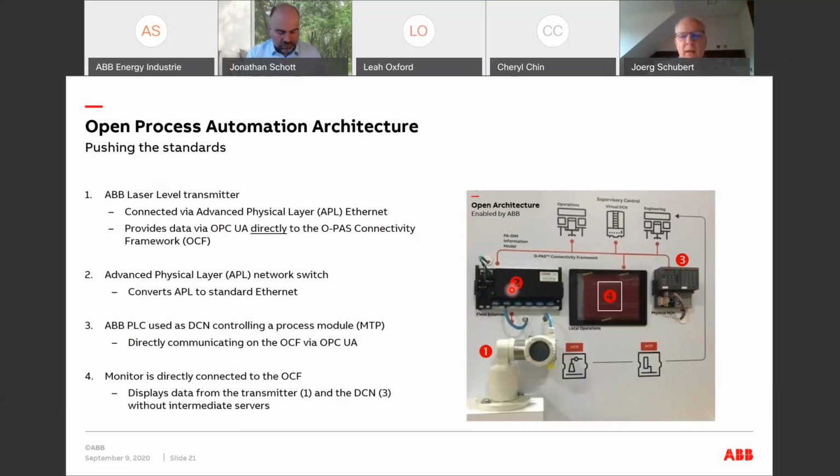It allows to stretch the Ethernet into the field and supporting the deployment in hazardous areas, including instruments that are sitting in zone 1. So you talk Ethernet into these APL switches, and then you have spur connections, and you see several ports here, and each of these ports would connect one field instrument to the assembly.